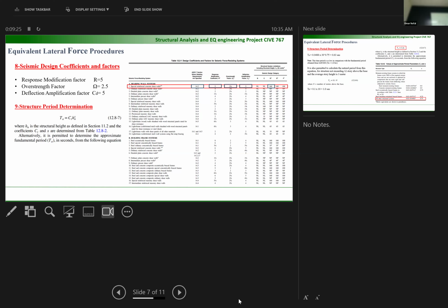Or we make it an inelastic design, like the building is gonna move and we are gonna allow the building to have inelasticity. Like we are gonna have some cracks and it's gonna open and it's gonna return to its original position, but it's not gonna fail. And after the earthquake, we are gonna repair it. So it's gonna allow us to design the building under low seismic force, okay? And this is a less expensive design. So what we are gonna have is gonna be